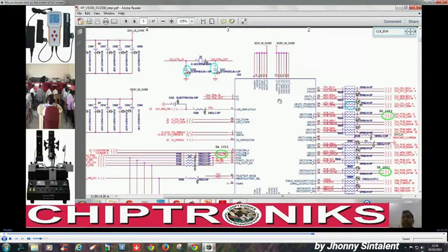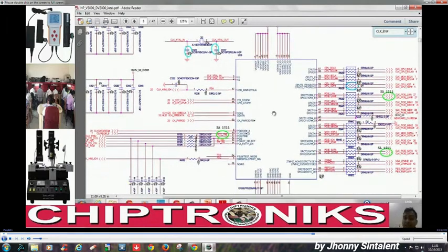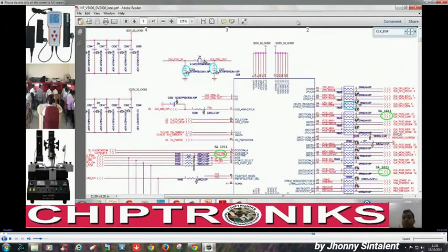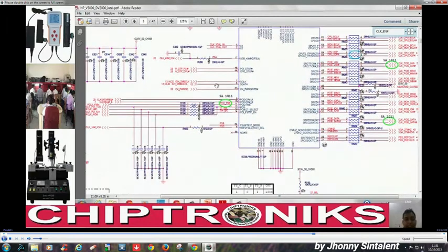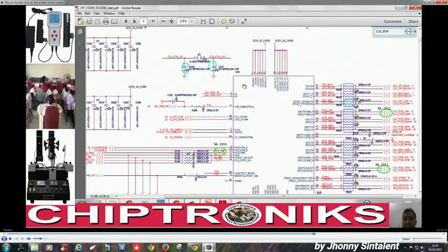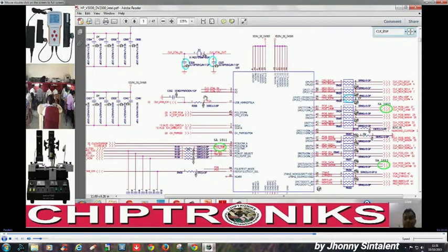If this 48 megahertz sine wave is not coming, the clock generator is not working correctly, and in that case we have to see the inputs: supply, crystal, CK power good and CPU stop. Once we check these, my output should come over here. If it's not coming, then your clock generator is faulty, right?